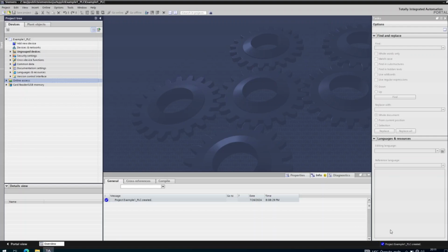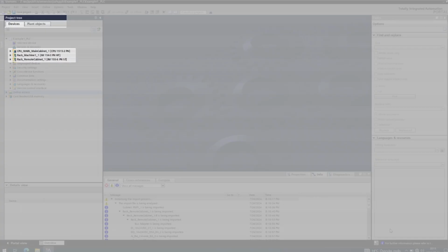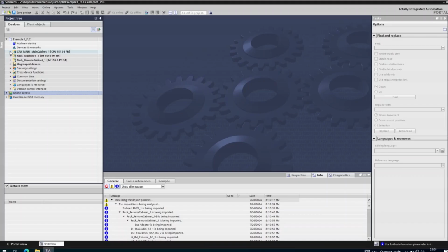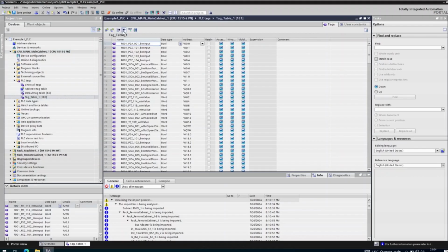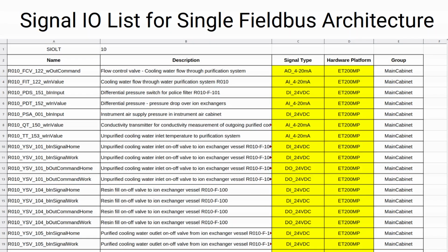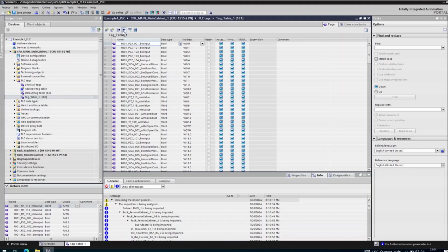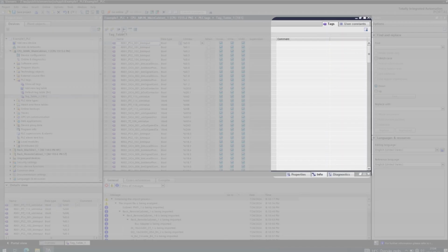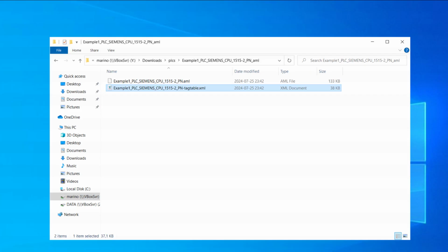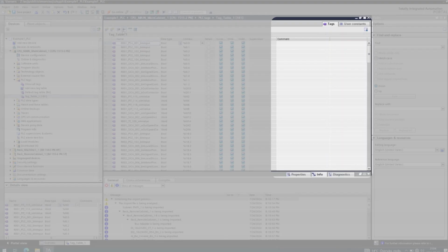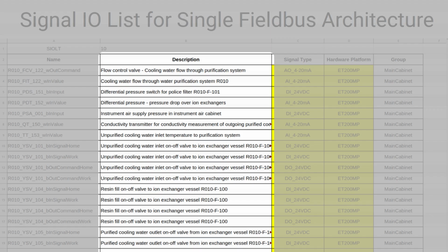Upon completion, the racks of your PLC will be shown in the Devices tab of the project tree. During the import of the hardware configuration, TIA Portal creates the Tag Table 1 which corresponds to the IList uploaded in the PLC generation process in PLC Creator. However, the tag comments are not part of the hardware configuration, and they shall be imported from the tag table file provided by PLC Creator in the same zip package. The comment column in Tag Table 1 corresponds to the description column in the PLC Creator IList.